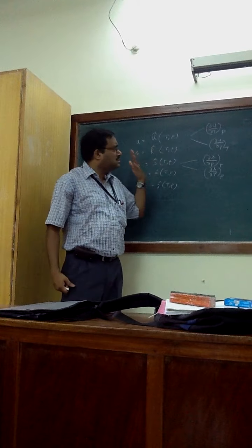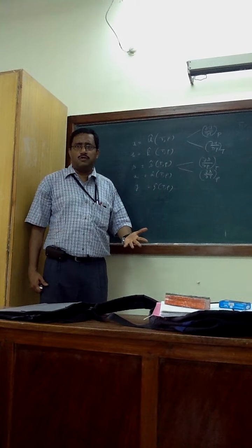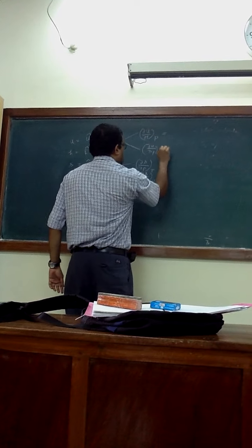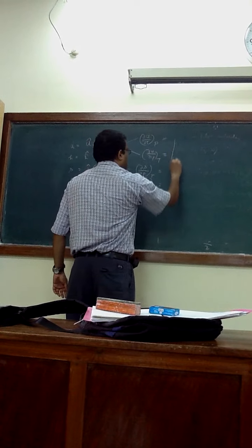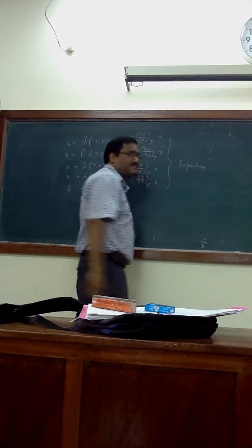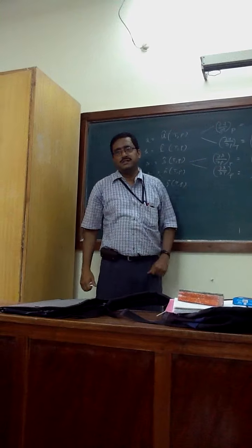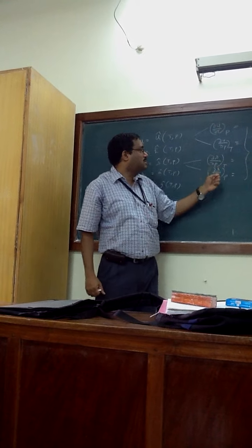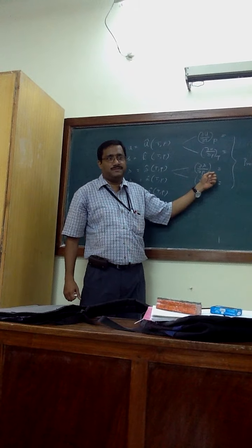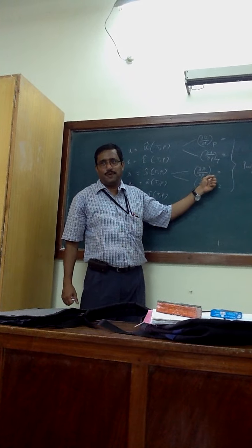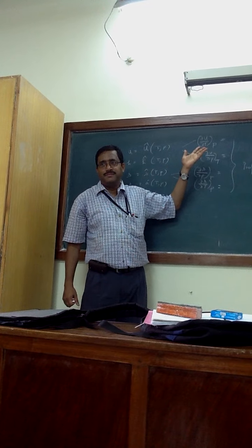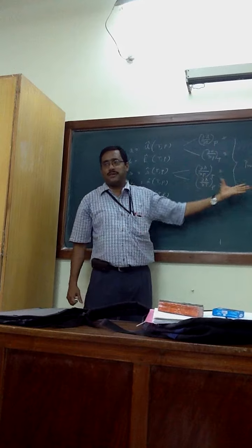Sometimes we got some exact formula in terms of Cp, and this is what you got on the right hand side as a function of properties. What kind of properties did you get? For example, ∂S/∂P at fixed T, Cp. If you have the TV plane, ∂U/∂T at fixed V, Cv. So you get it in terms of thermal properties.